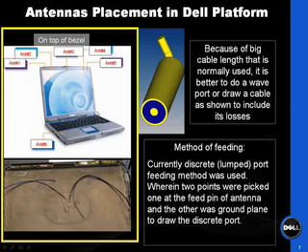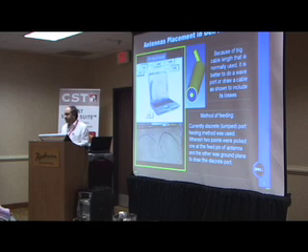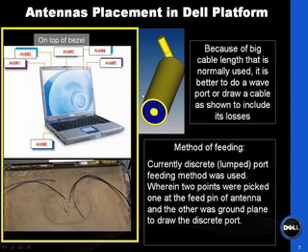So then you use lengthy cables to go all the way to the motherboard. You can see the cables coming here, antenna 1, 2, 3, 5, 6, going all the way to the motherboard. The cable can run as much as 350 to 700 mm. So the best way to do the feeding, if you want to use a simulation for the laptop, is by using the waveport method. Actually, using a simulation tool, you can even make your own cable like this one. Jeremy has helped me in making this cable, and you can apply all the properties.